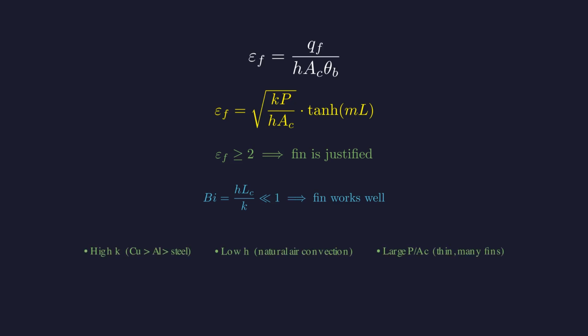Fins work best with high thermal conductivity like copper or aluminum, low convection coefficient like natural air, and a large perimeter to area ratio.